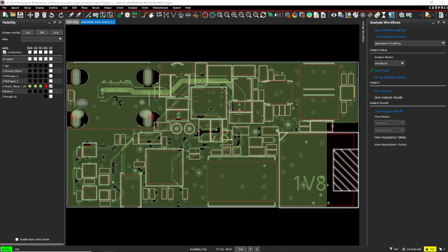First, let's immediately notice how the engineer tried to keep the reference plane continuous and therefore with a low impedance. Having a nice continuous plane giving us a low impedance also reduces potential noise and EMI. The less copper on this plane, the higher the inductive loop path that certain currents need to take, and therefore the higher impedance of the plane. All right, so that's all I have to say now for this design.